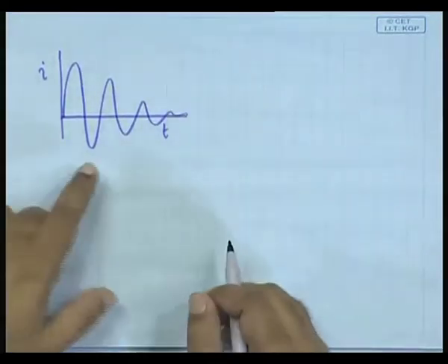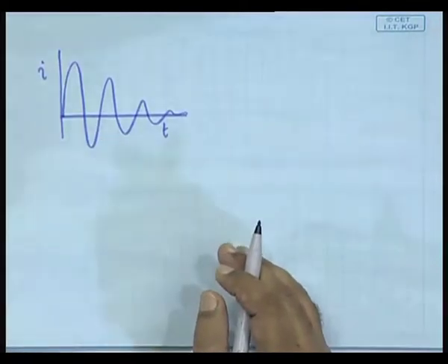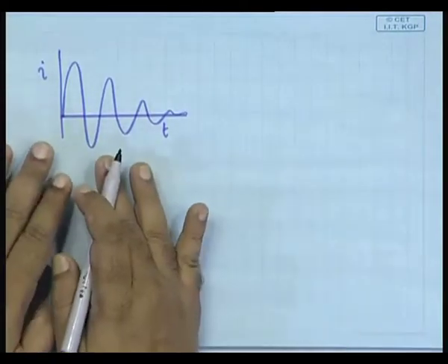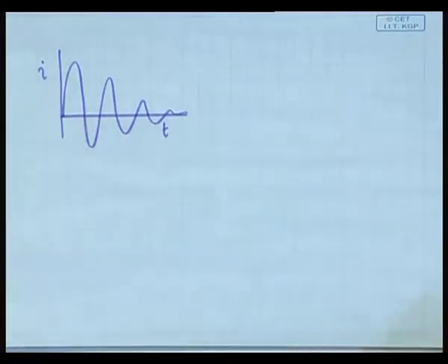In this case also, you cannot define the time constant in the same way, but there is an exponential term. So, instead of time constant, we can say that there are certain characteristic times in the system. One characteristic time relates to the time constant as obtained from the exponential. Another characteristic time relates to the period of the sinusoid. Okay. So, in this system, therefore, there are 2 characteristic times. So, instead of time constants, we will try to think in terms of characteristic times.